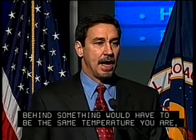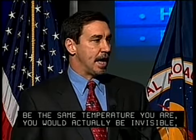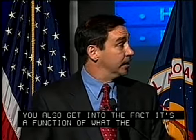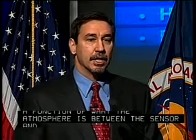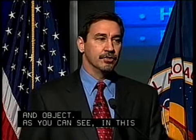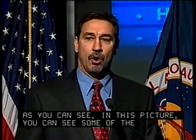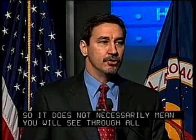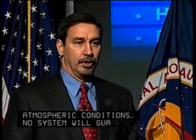You also get into the fact that it's a function of what the atmosphere is between the sensor and the object. So as you can see in this picture, you can actually see some of the clouds in the background. So FLIR does not necessarily guarantee that you will see through all atmospheric conditions. In fact, no EVS system can guarantee that it will see through every atmospheric condition. So there are weather issues that you have to worry about.